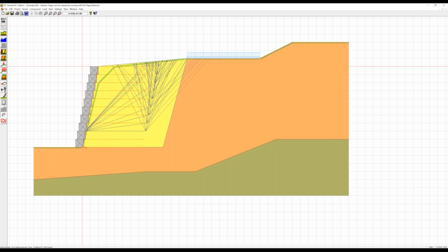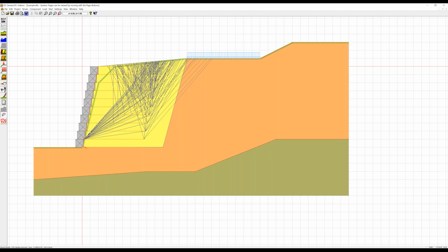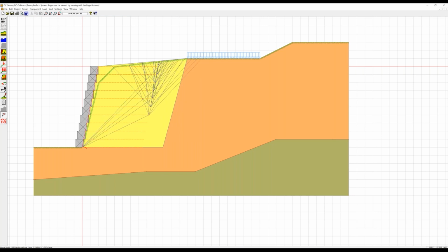They are not lengthened yet. So this is quite a complex calculation, which does a large iteration for all the possible blocks, which might be the critical failure plane. Here you just saw that there was a little lengthening of the geosynthetics. Now we have the iteration of the friction circle. These are the centers of the slope stability circles. And then the analysis is finished.